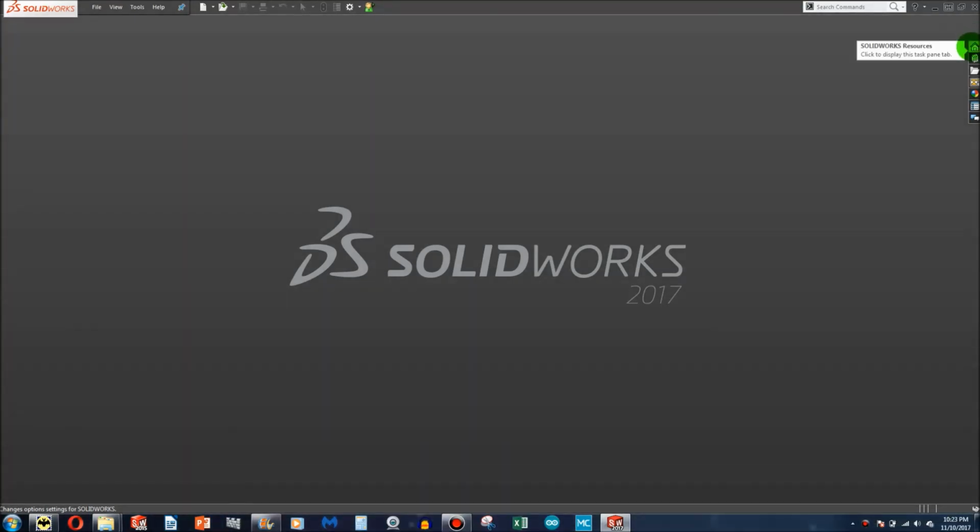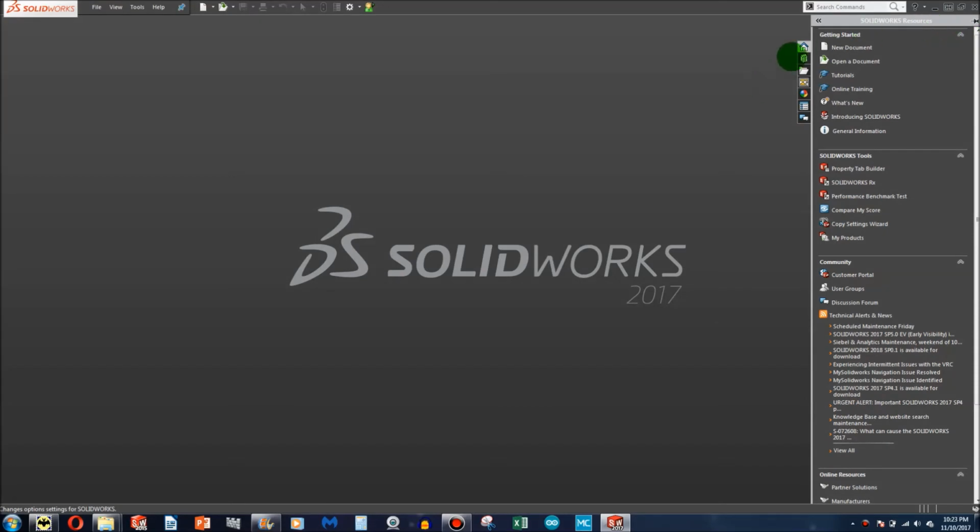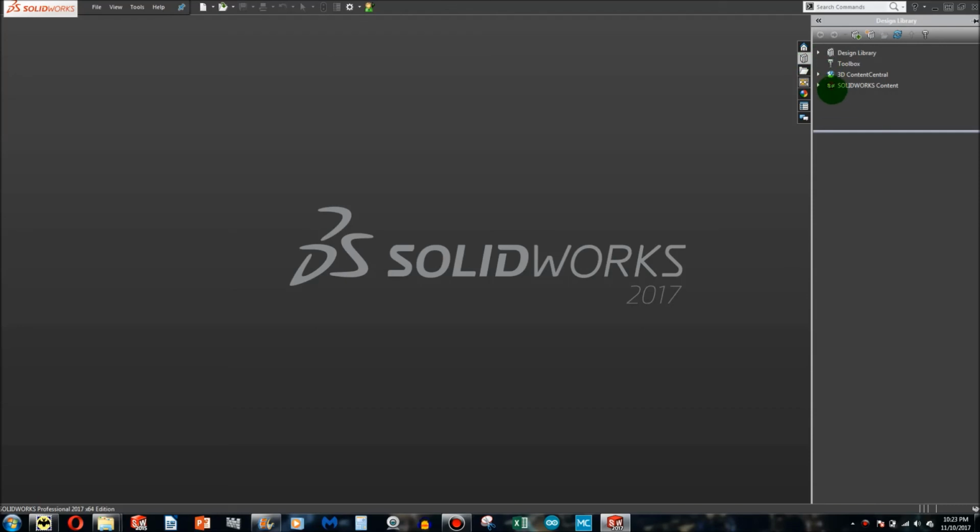Over here on this menu to the right, you can click on the house, and it gives you Home with SolidWorks resources. It gives you the opportunity to make a new document like we went over before. Open a document, tutorials, do some online training, a few other resources that you really don't heavily use very much. SolidWorks RX helps you track errors and even record your screen if you're finding a recurring problem. You can go to the design library where they have some links to the web, and that you can pull solid models, gears, things like that off the web if you want to.